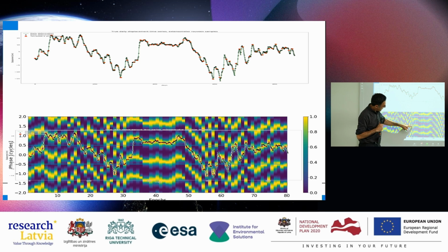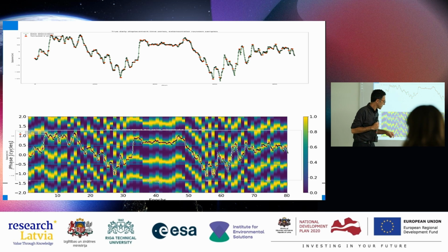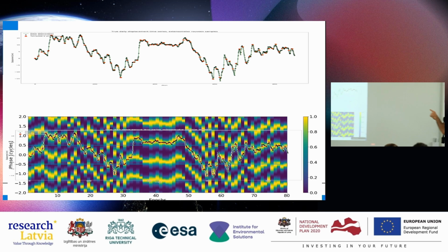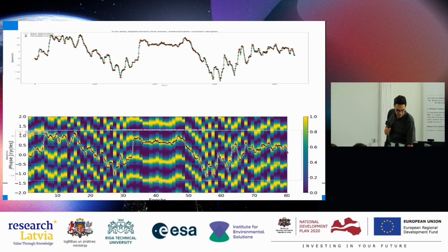Now, if you look at this from, for example, this location over here, and you would follow the yellow lines here, then you would never choose to go from here to this step, right? You would simply continue. This would go on, and then maybe here you would decide to go down, right? So this jump, I think that happened over here within 1, 2, 3, 4, 5, 6, 7, 8, maybe 9 days, more than a centimeter of uplift would be completely missed with this data, simply because the signal is so dynamic. And this is in the case that I have no noise. I have perfect data because the red dots are still in the center. So here you can see the magnitude of the problem.